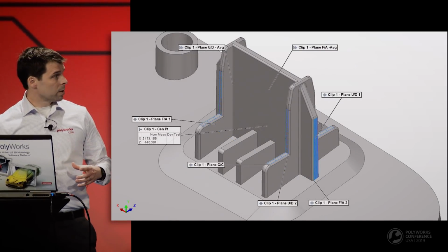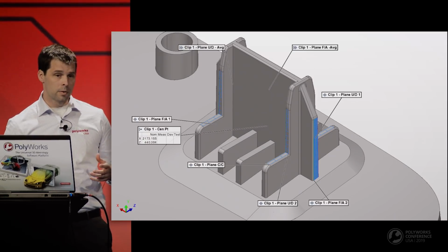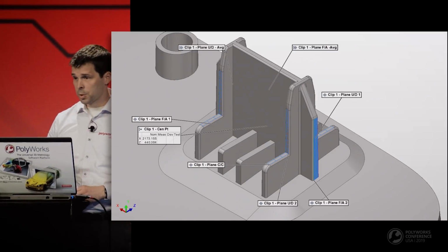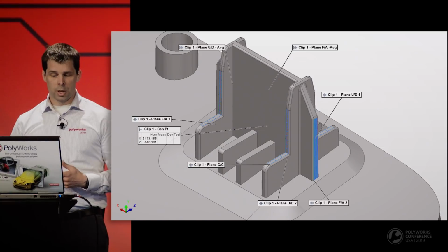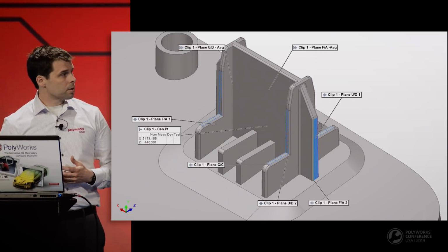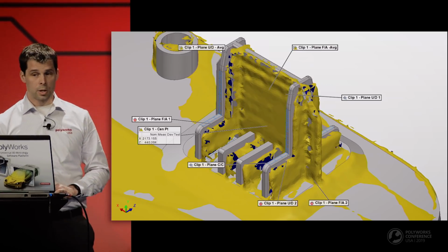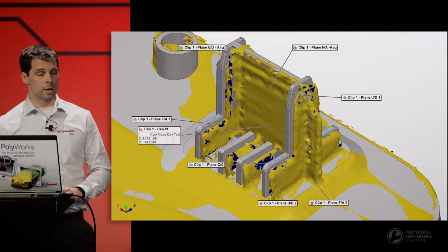One way to determine this center point would be to create small planes on all the contact surfaces and then use constructed features to derive the center point. The first issue we encounter with this method is that constructing all of these planes and constructed features is very time consuming. In addition to the complex setup, extracting these features is problematic.